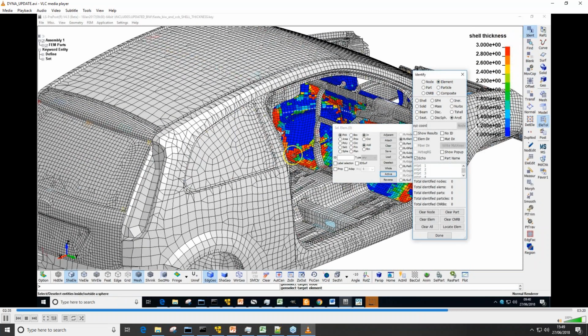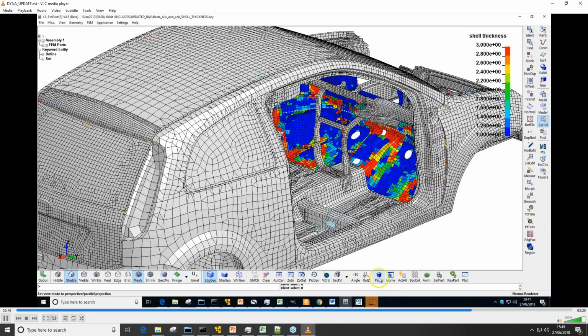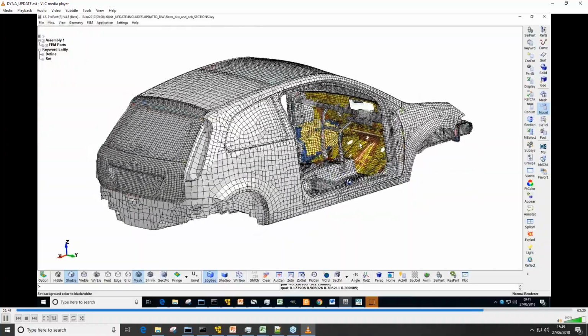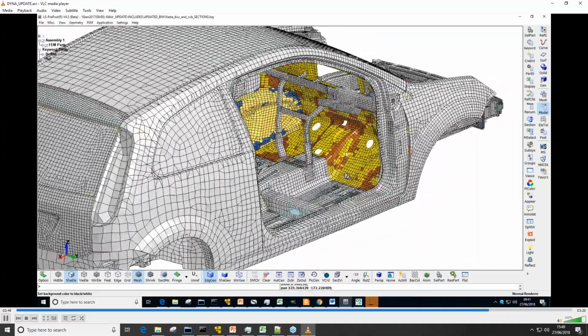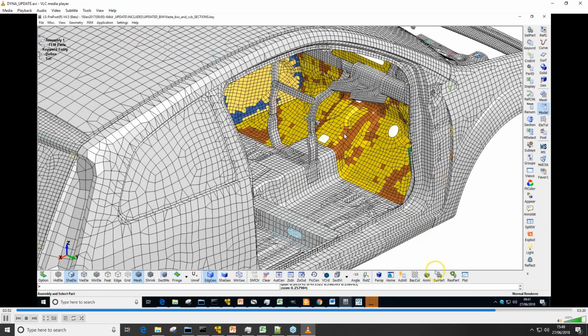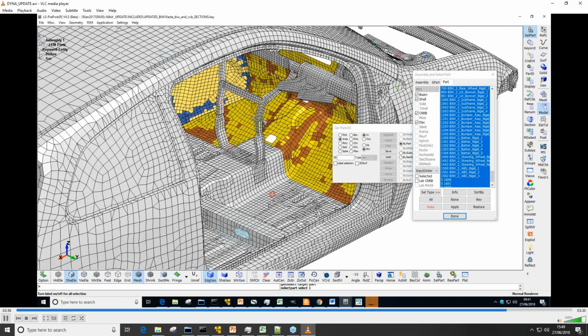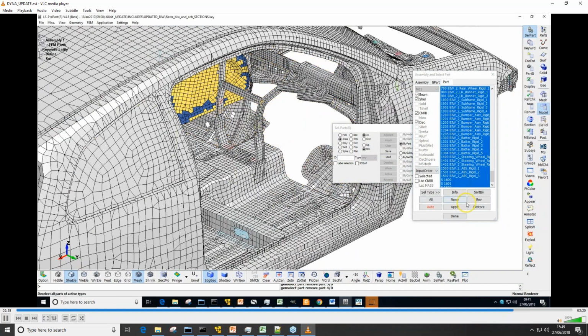One of the key things I find is the other option we'll show in a moment, where we split it into parts, is quite useful if you want to then do further subsequent iterating. You get some more discrete thickness results, and you can edit them more readily afterwards. So you can see here the parts being broken into different properties. I've kept this quite simple just for this example with a very large increment of 1 millimeter.